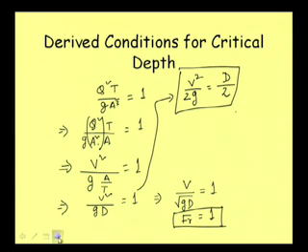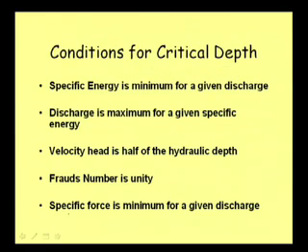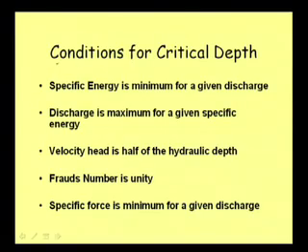Combining all these relations, we are now in a position to summarize the different relations that we have got, that is, the conditions that we have for critical depth. So, what are the conditions for critical depth? First, of course, the specific energy is minimum for a given discharge, and we should always remember to mention this particular point, that is, specific energy is minimum for a given discharge, and that depth is called the critical depth.